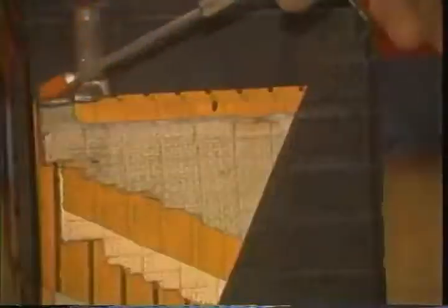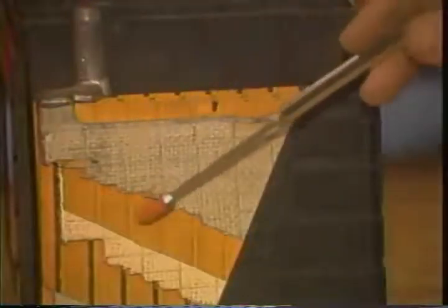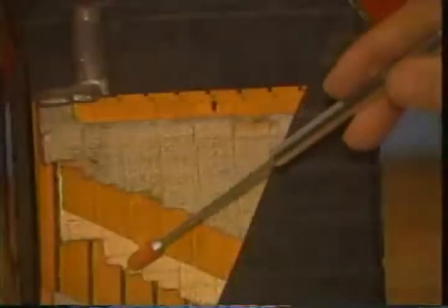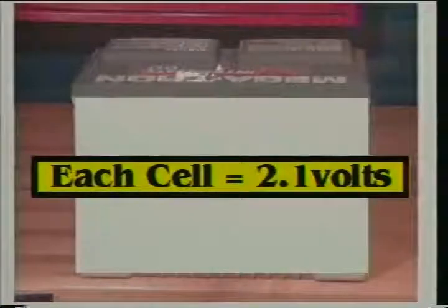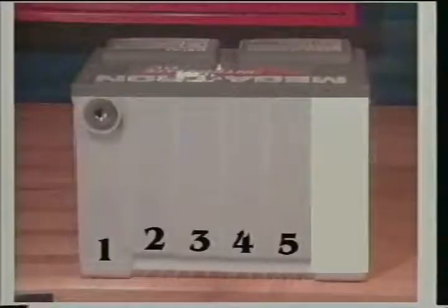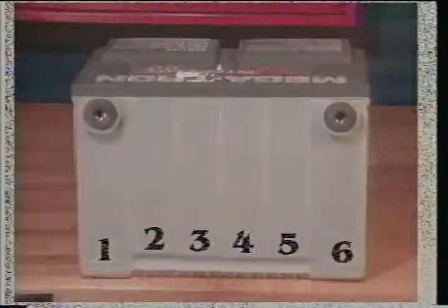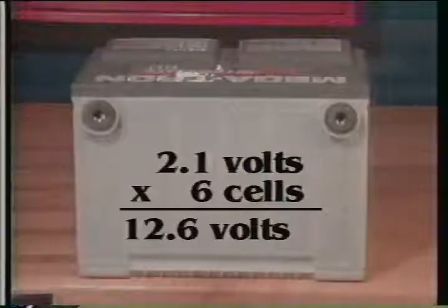This cutaway shows how an actual battery cell is made. Note the plates are separated by insulating separators. The positive plates, the separators, and the negative plates are sandwiched together. Each battery cell produces roughly 2.1 volts. Since modern car batteries normally have 6 cells, the battery is called a 12-volt battery, but more accurately, it produces 12.6 volts, 2.1 volts times 6 cells.